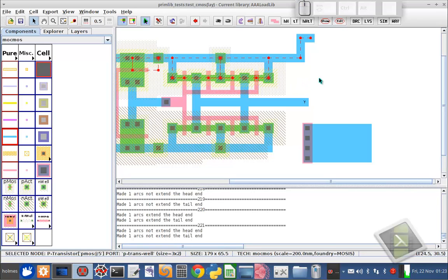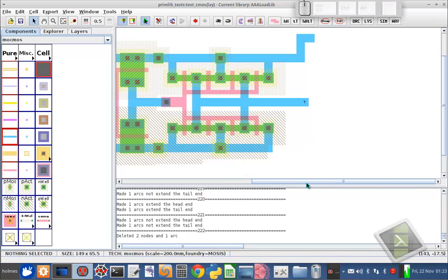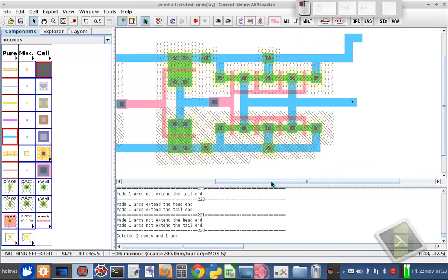But what you can see has happened, and again, this is more of a manufacturing issue than it is a design issue. In the creation of this layout, I have these ragged geometries. And for design for manufacturability, although all the rules are satisfied, DRC is satisfied, it's a perfectly valid design. In general, these ragged edges create more problems than they solve.